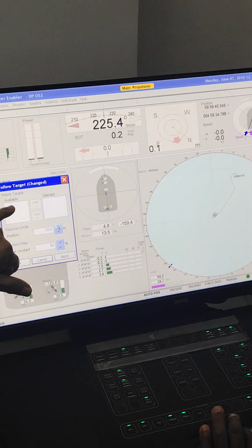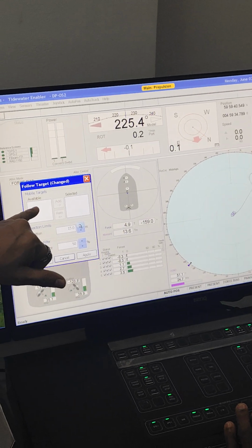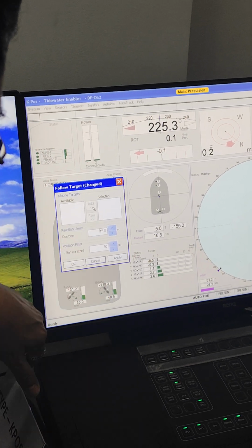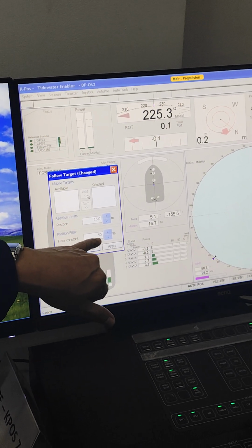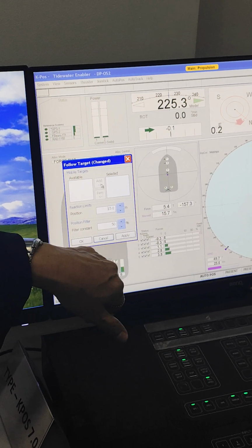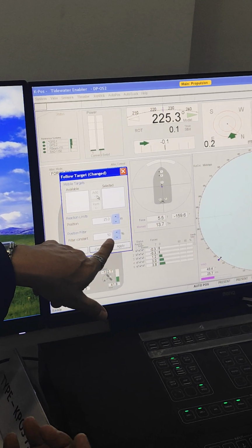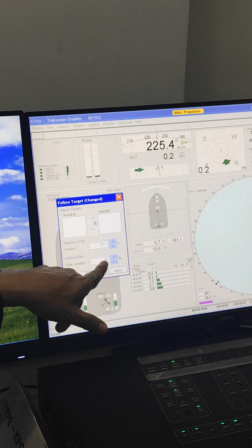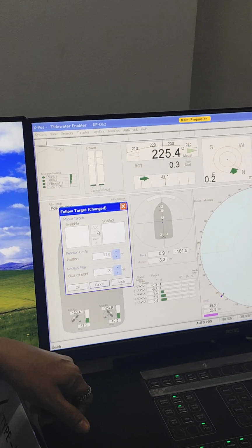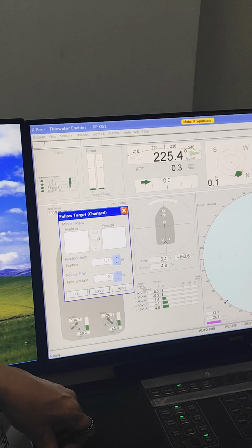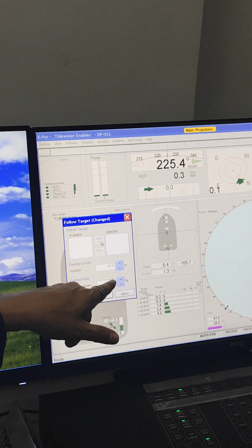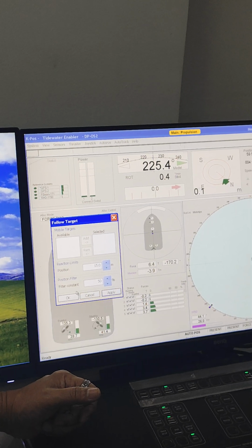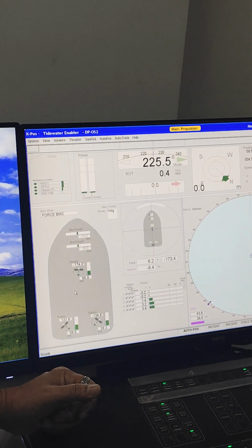What are those available beacons? When the ROV says I'm beacon 1, then you have to click add and highlight number 1, and it will transfer in here. And then the filter, of course, at 50% all the time, meaning the gain, the reception of the beacon. If the noise is too strong, you have to increase. If the density of the water is brackish, you have to increase. Anyway, that's controlled by the system, and then apply. And okay. And next.